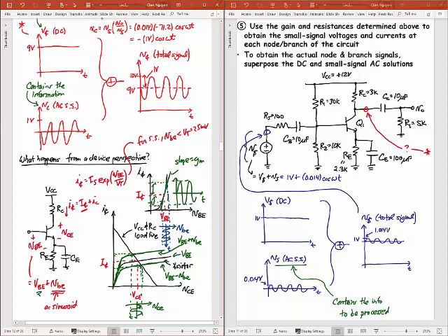Okay, so go ahead. Really quick, if VBE was like even a third or a fifth, if it was a fifth here of VT, wouldn't that be like 1% of the IS? Yeah, it would start bringing you closer to the nonlinear region. But I'm even okay with it being 10 millivolts or something like that, or even 20 millivolts or something. I mean, my example was 14 millivolts already, right? But in most cases, it'll be much smaller than that, because we're really trying to amplify extremely small signals.